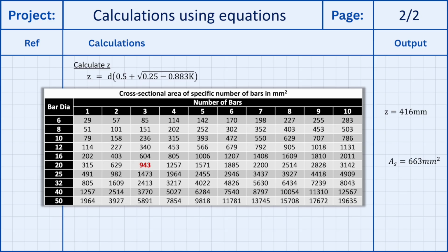and so on. The choice of bar diameter and number depends on the geometry of the cross-section and the requirements for cover and spacing between bars. For example, it could be difficult to position 4 bars with 16 mm diameter in a 300 mm wide cross-section. Provision of 1 bar with 32 mm diameter is not suitable as well, because 1 bar is usually only used in elements with no structural importance such as lintels. Therefore, the most suitable choices for us are 2 bars of 25 and 3 bars of 20.